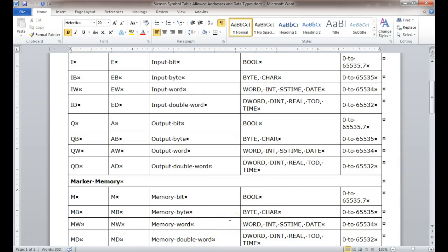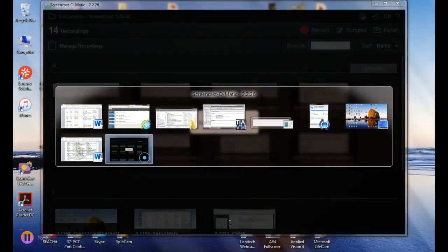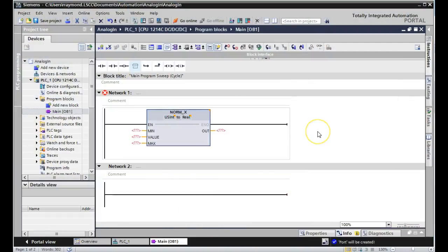So what we'll do is, like I said, guys, I might have to go back and research this a little more. What we're going to do, of course, is come up here and assign it a minimum value. So you can actually set the reference to a minimum value, right? You understand? So of course our minimum value is going to be 0, and then our maximum value is going to be what? 1023. That's not too bad, is it? And then of course, where are we going to get our value from?